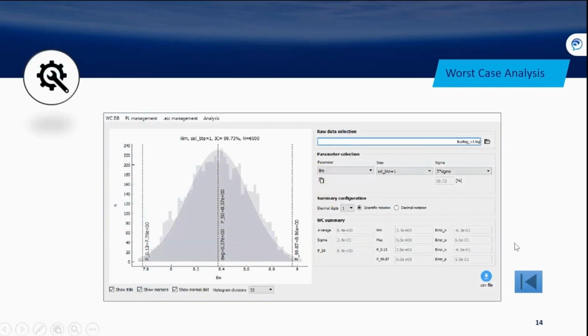The worst case analysis is based on varying the tolerance of the components with a Monte Carlo method. It will take into account the drifts in temperature, aging, and radiation of every single component, and it will try to run a lot of cases to find the worst case scenario.